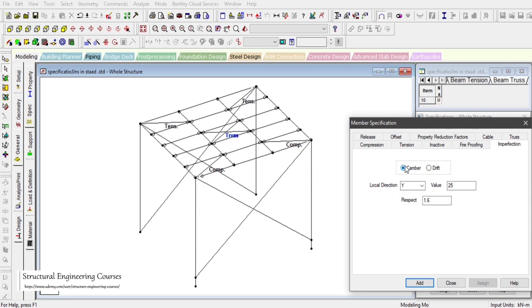And one more thing that I'd like to add here: when we are considering the camber, there is this respect value called 1.6. Actually, STAAD calculates the epsilon for the calculation of this pre-camber, and when that epsilon according to this respect value is not considerable, then STAAD does not consider any effect of this pre-camber.